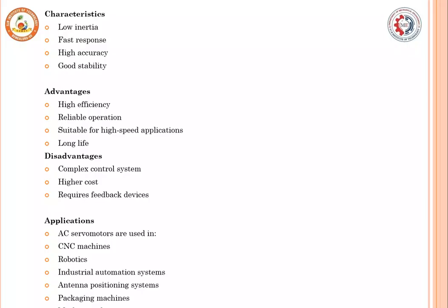The characteristics of the AC servo motor: the inertia of the motor is low, the overall response is fast, it has high accuracy, and the overall stability is good. The advantages are high efficiency, reliable operation, suitability for high speed applications, and a long life. The disadvantages are complex control systems, higher cost, and the requirement of feedback devices.